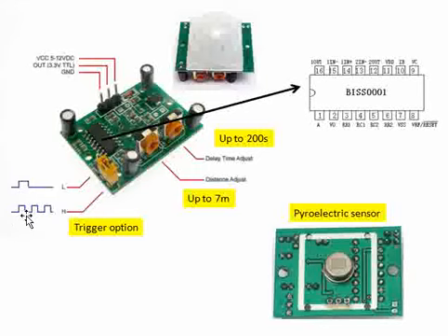So it has reset, but the target, the human we are talking about here, is still in front of the sensor, and then again it goes up, and then again it retries and goes up. That's how it is here. In the other option, it does it only a single time. So there are two options. You can change your sensor settings to either of these based on what you're intending to do in the end application.